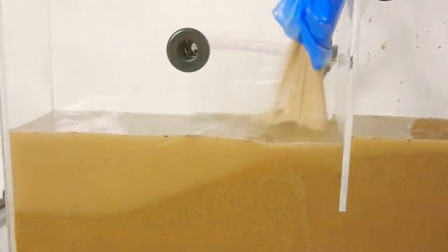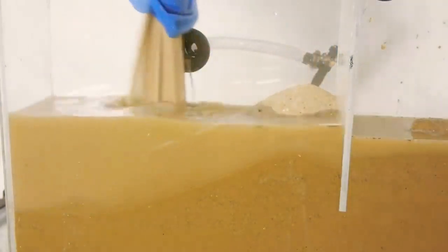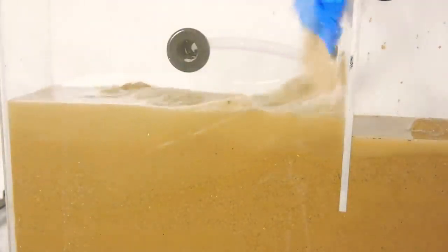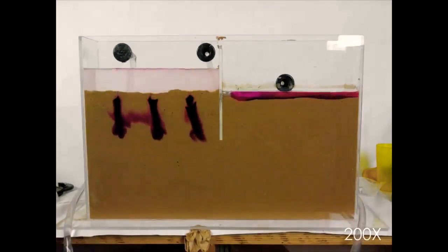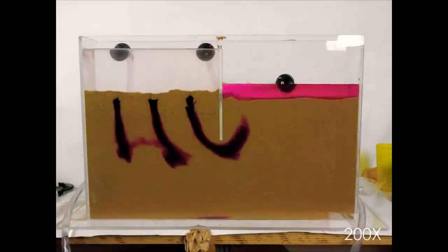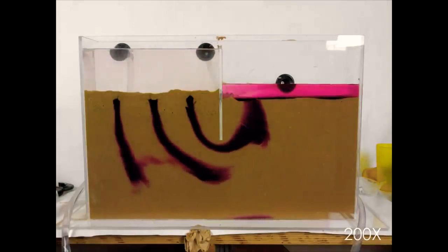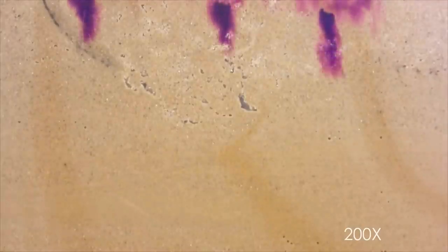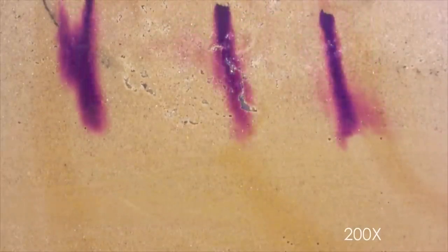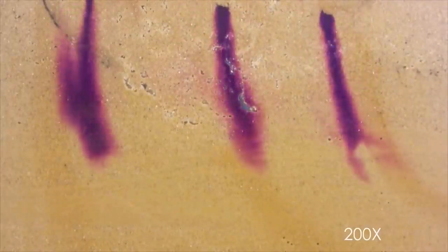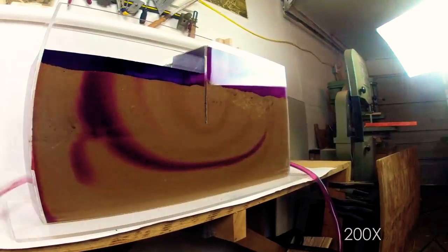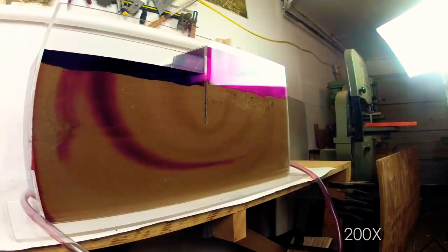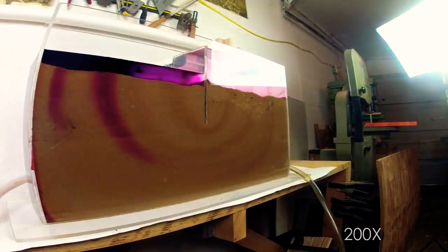But let's look at a non-erosive example of groundwater movement first. This is from a video I made before the channel was even called Practical Engineering. Water's flowing from the left side of the demo, under an obstruction, and over to the right. Notice two important things. First, the movement of the water is slow. There's not a lot of open space between all that sand, so it takes time for water to flow through it. Second, the sand is confined. Even if it wanted to move, there would be nowhere for it to go. If those two conditions go away, that's when sinkholes happen.